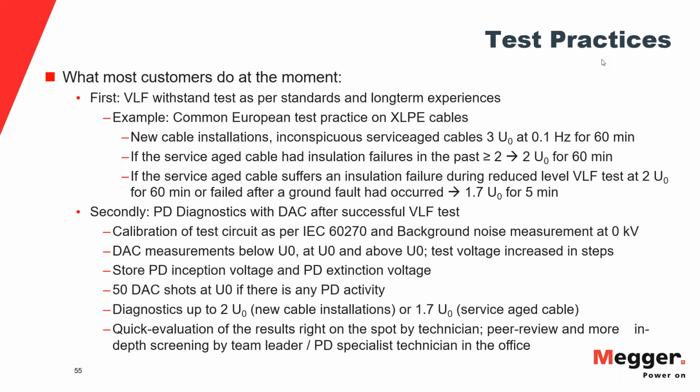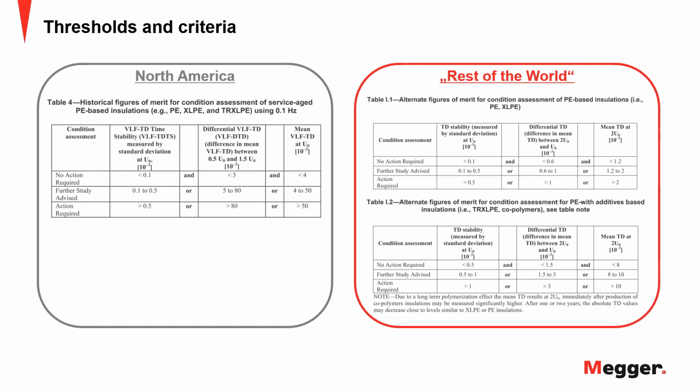The short answer is yes, there is a reference guide. Robert talked about some of the limitations of tan delta, and he popped up the slide. You have a starting point, taking into account those limitations, such as mixed cables. It has been determined that you probably should not tan delta test on new installations.